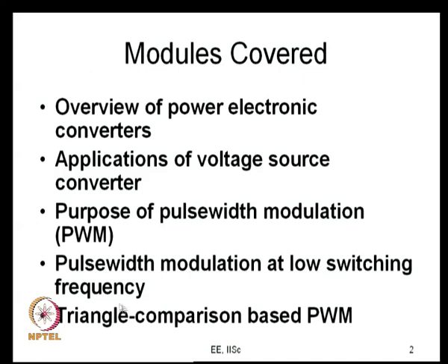We considered the situation when the voltage source inverter switches at a low frequency. Now, why? Firstly, this was very relevant a few decades back, when the power semiconductor devices available could not switch at very high frequencies, they switched at rather low frequencies, something like 400-500 hertz. But the modern devices switch at much higher frequencies. Nevertheless, this is still relevant in certain contexts such as high power drives.